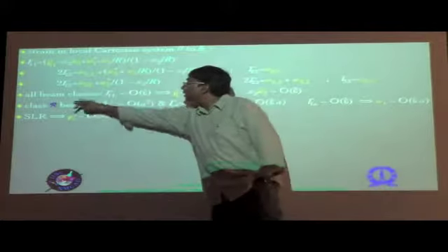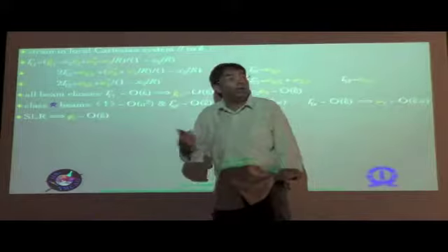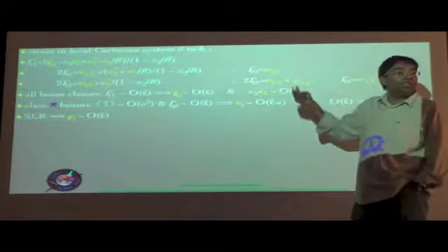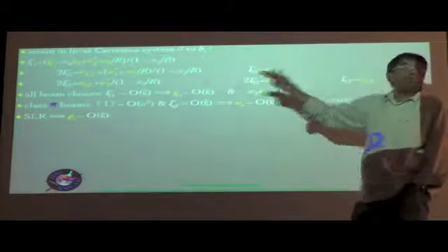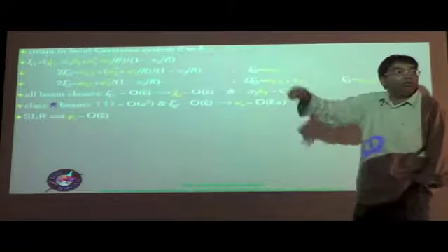So in this case, it is class R beams, we have small local rotation and Pi is of the order of epsilon hat. Basically, these are the terms which contribute to the local rotations, and you can see quite clearly that they are indeed of the order of epsilon hat. So there's no assumption involved, it's a fallout of the fact that we are dealing only with small strains.